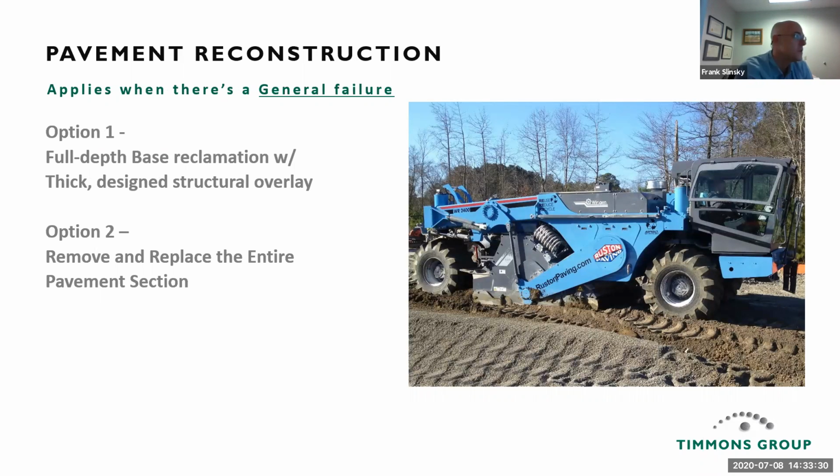Pavement reconstruction. This applies when there is a general failure in the pavement. Option 1, full depth base reclamation with a thick design structural overlay. And then option 2 is remove and replace the entire pavement section. I'm not going to go into that. I think that option 2 is more self-explanatory. We're removing all the pavement and stone and coming back with new.